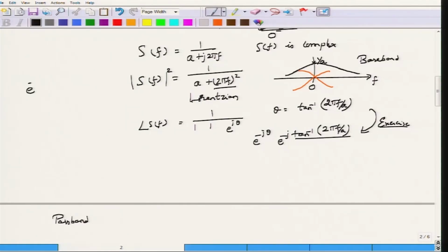So, this e to the power minus a t u of t, whose Fourier transform is centered at f equal to 0, right? This is the Fourier domain. So, a signal whose Fourier transform is centered at 0 is called a baseband signal, because much of its frequency content is located at f equal to 0, or the DC. However, there are situations when you consider signals whose center frequency is located not at 0 frequency, but at some very high frequency that is greater than 0.